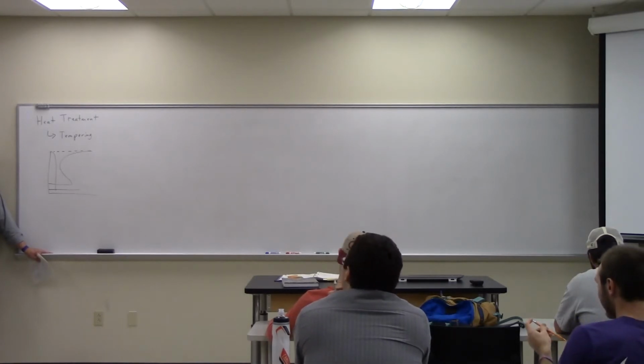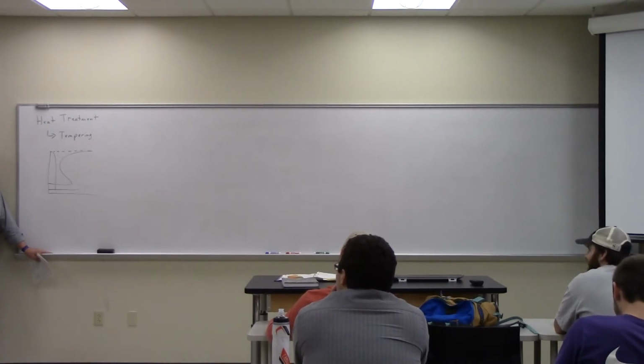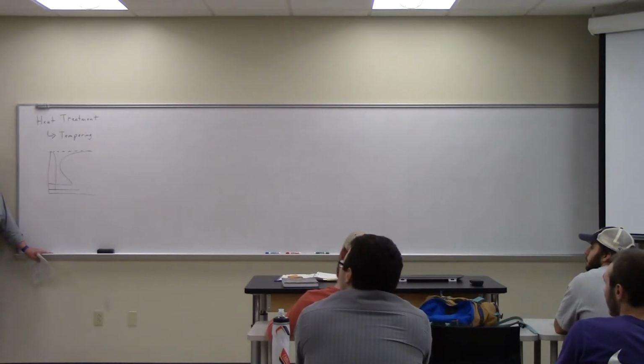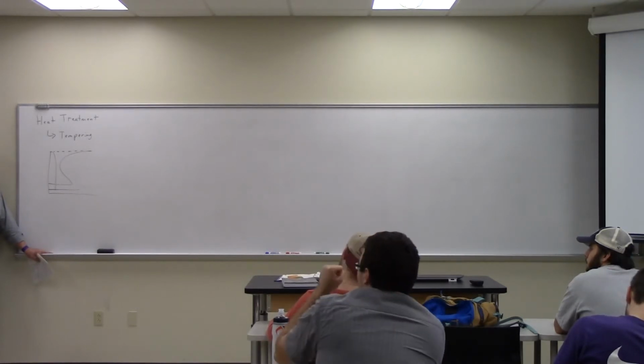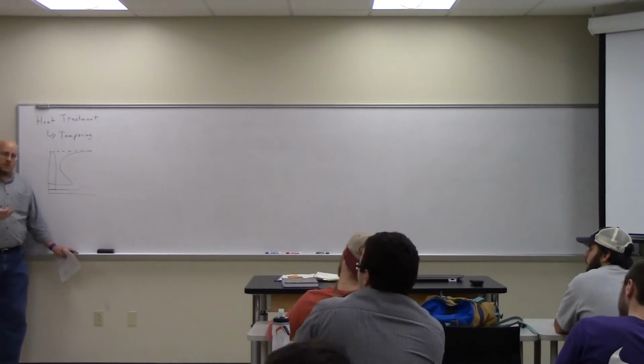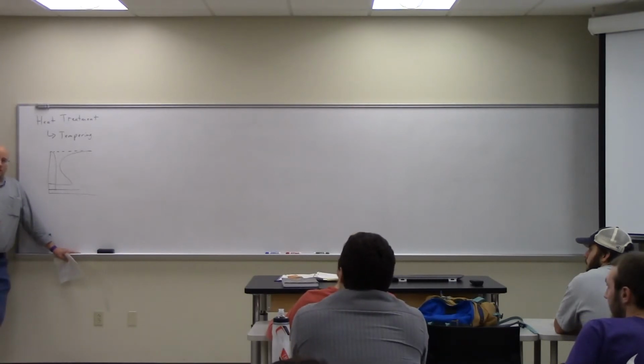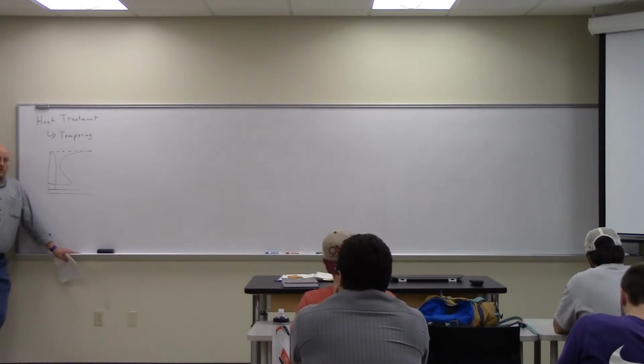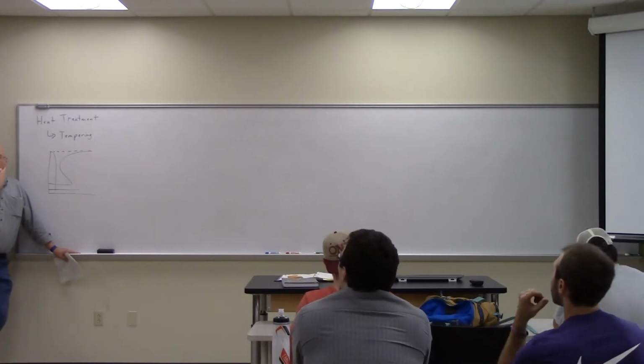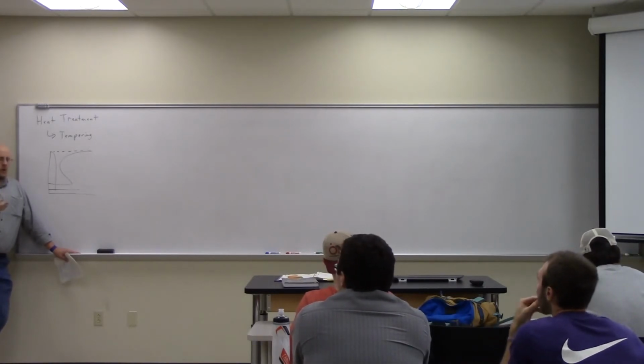We're going to do the heat treatment, so you can be quiet now and just let us continue the class. Why do you want martensite for the blade of a razor? Because martensite is brittle but very hard. That's a katana. It's an extremely hard material. Hardness is when you poke it with a pin, it doesn't make a dent. So we want hardness for a razor blade, so that when you hit a whisker, it doesn't dent the blade. You want a nice sharp edge.